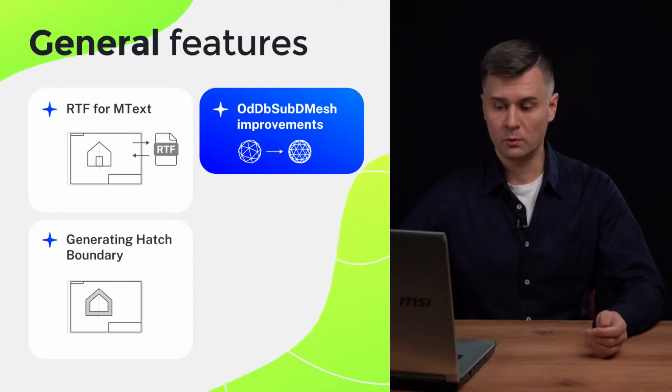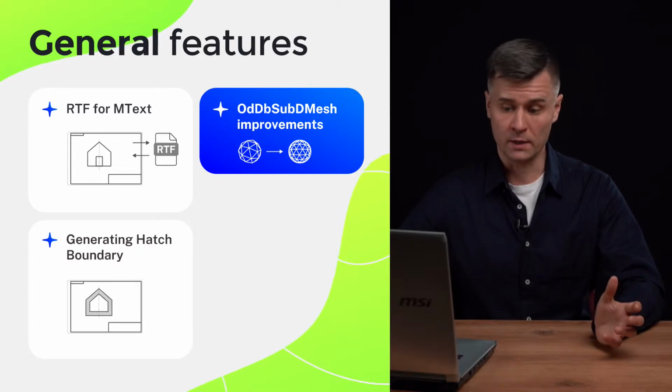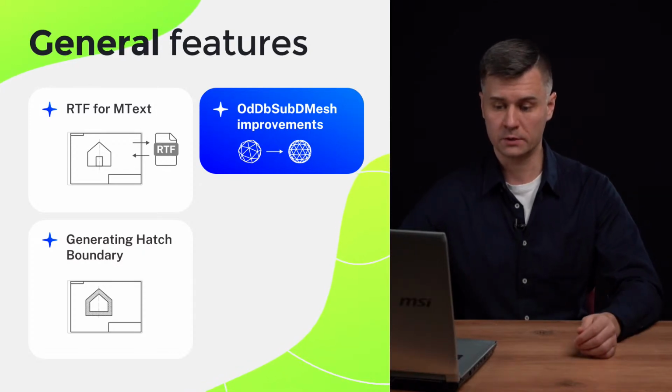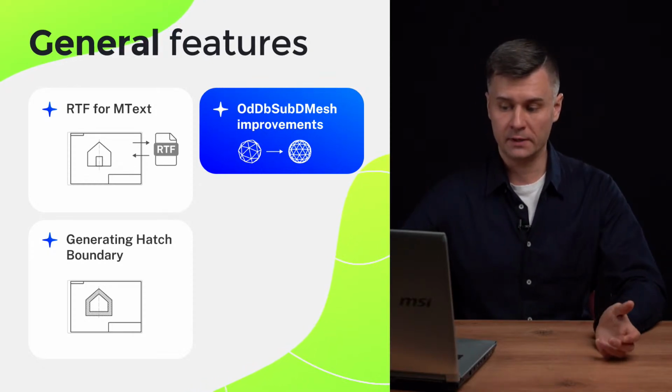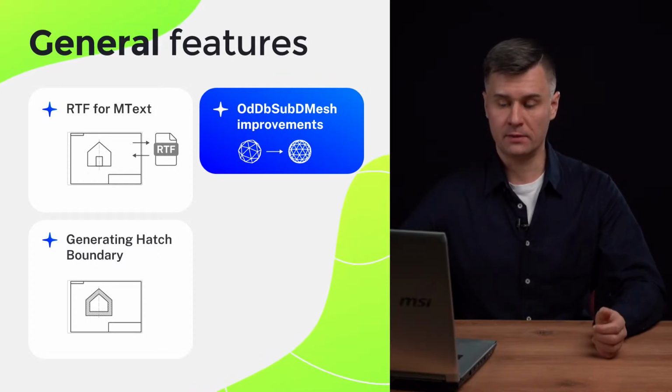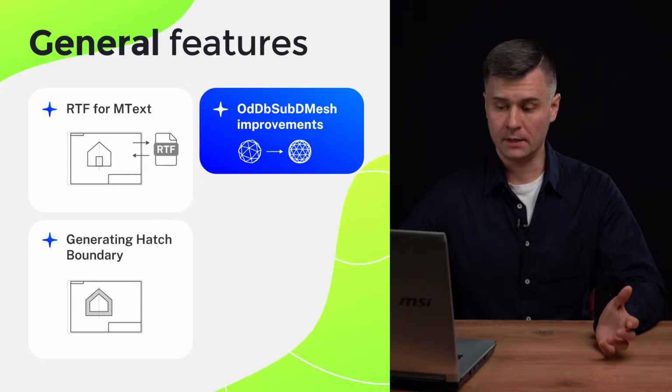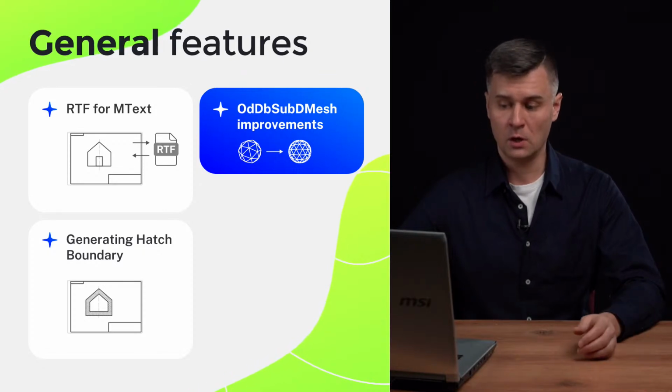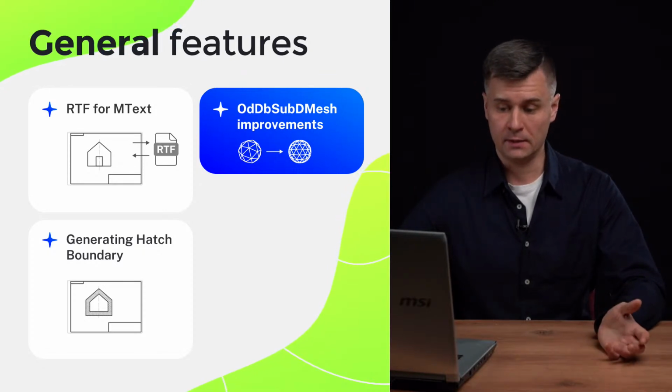The conversion mode to a smooth body merges some neighboring surfaces into one surface, so that's how it works. These smoothing optimization features are very helpful in case you create your 3D entity from a mesh. It significantly reduces the number of faces in a 3D entity and increases performance for all operations with this entity.